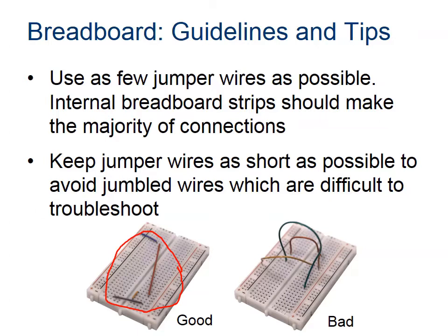One of the ways that I like to build circuits is, when I'm looking at a schematic or wiring diagram, I cross off the element on that diagram as I create it. So for example, I'm going to put my power in over here, and then I'm going to cross that out on my schematic, and then I might put in some wires or a resistor or something like that, and cross those out on my schematic.